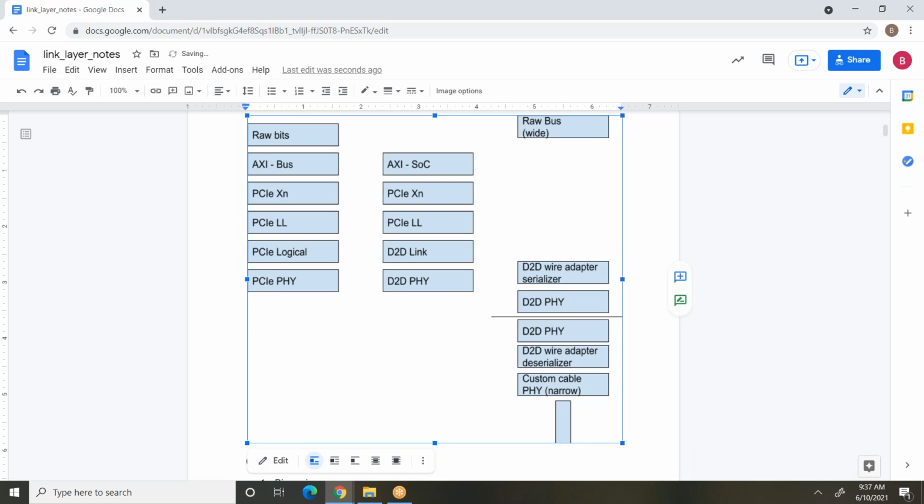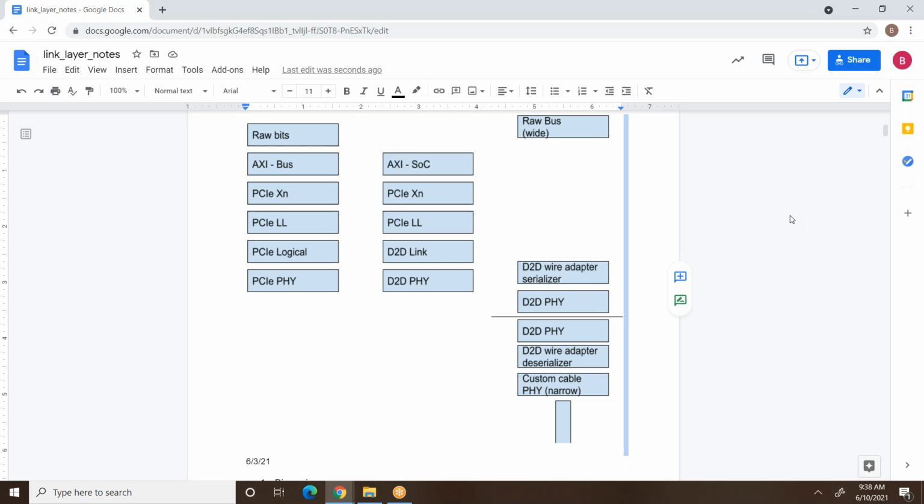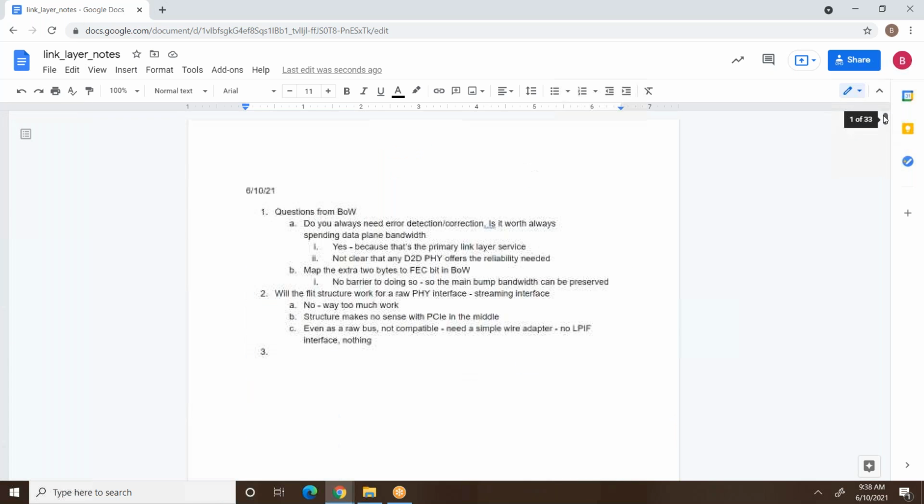It's a fixed engineered environment. So one service you could do at power up is set a training pattern which allows you to unscramble those lanes. I can't remember the details of Bow, but supposing the requirement was to go from a raw 512-bit interface to, say, a 16-bit interface, you could define a bring up mechanism to unscramble all that.